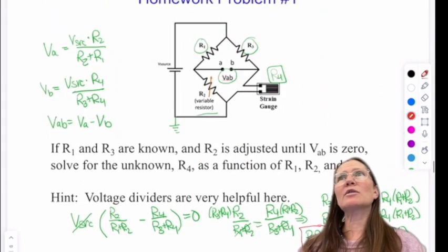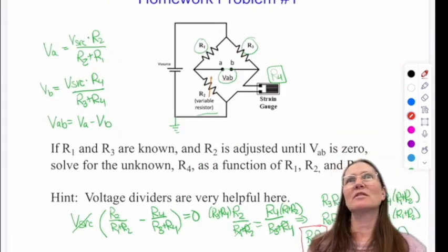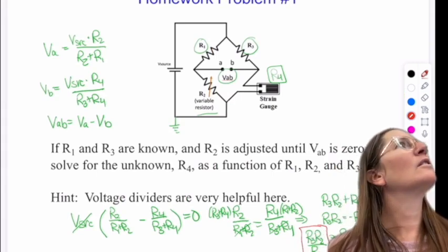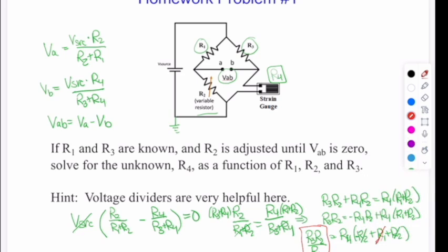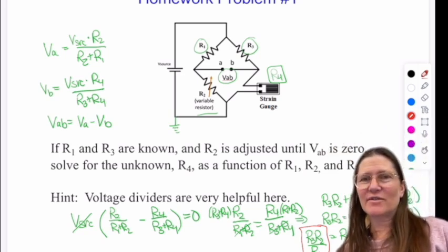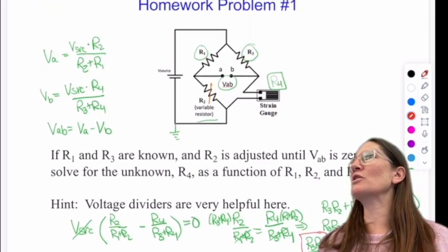Okay, any questions about the Wheatstone? Yes. So VAB, VA, what's VB? VAB is, whenever you see any variable that's a voltage and it has two subscripts, it means that it's taking the difference between those 2 points. So you would take the first and subtract the second. And that means that the red probe of your multimeter is placed on the first notation A, and then your black probe is put on B. So it's giving you a voltage difference between 2 locations. Is that more clear? Thanks for asking. Good question. All right. Any other questions about the Wheatstone bridge?